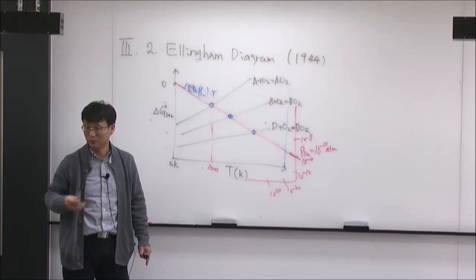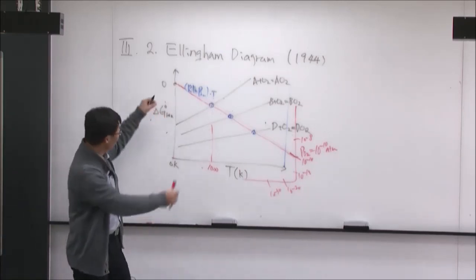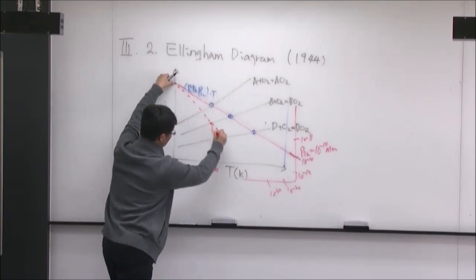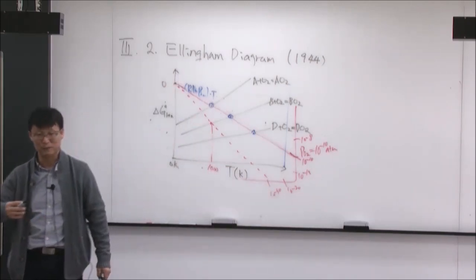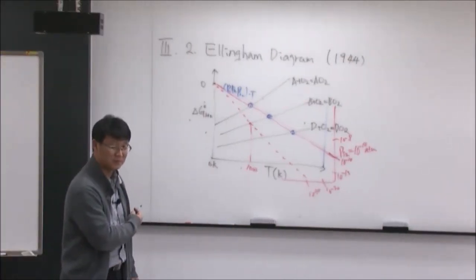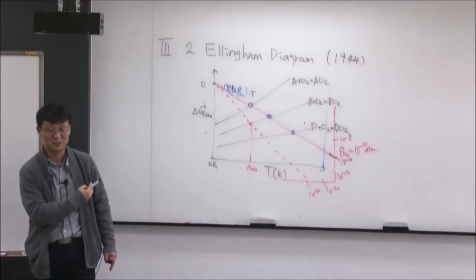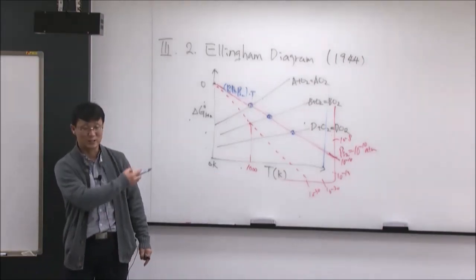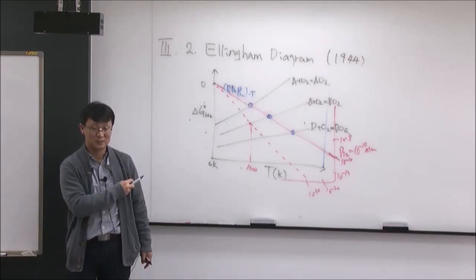Instead of doing the mathematical calculation, you bring this map and say, I have a ruler, so I draw the line from here, go through this one straight, and make a straight line. 10 to the minus 30. So if you are at 10 to the minus 30 or below, you don't have an oxidation problem. It's kind of the calculator at the time, an equivalent partial pressure of oxygen calculator. Everything is written on the side. The answer is there already. You don't have to do any mathematical calculation. That was the idea. It's a good idea, yeah?